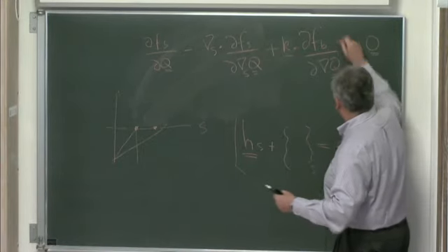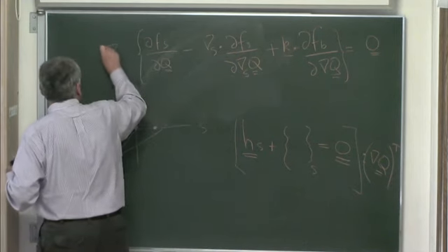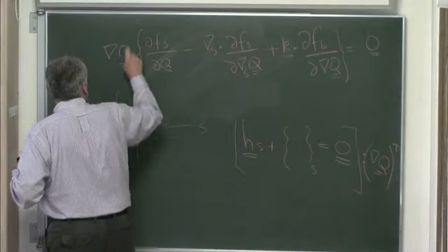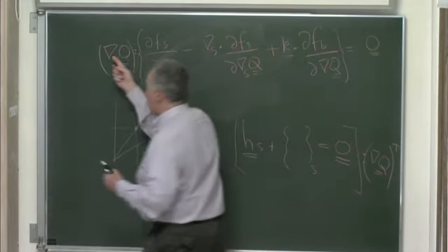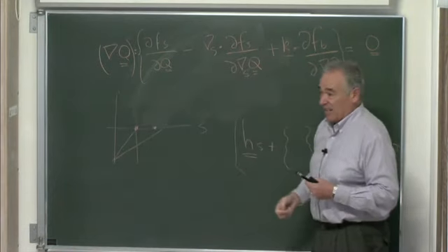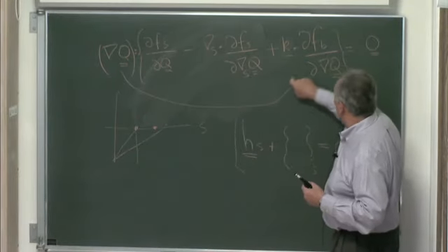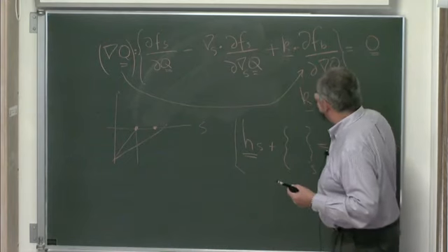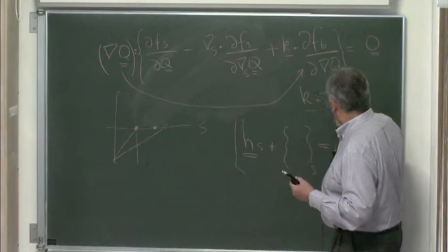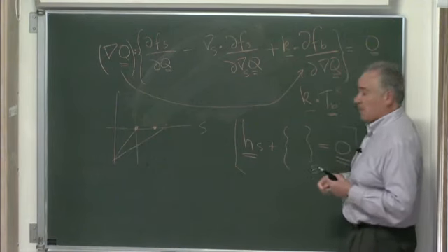Now, I get this equation, and I operate with this guy. If I multiply from the left, I don't have to take the transpose. So you can see that this times this, what is that? That's the bulk stress tensor, sometimes called Ericksen stress tensor.